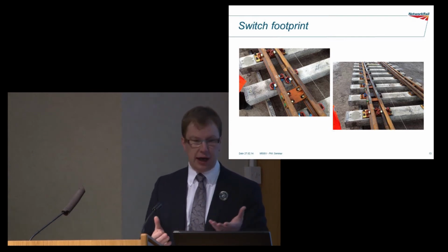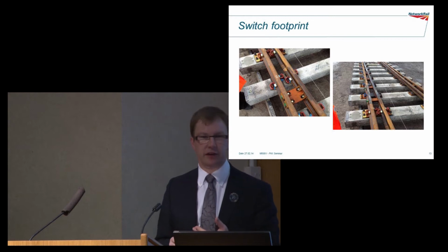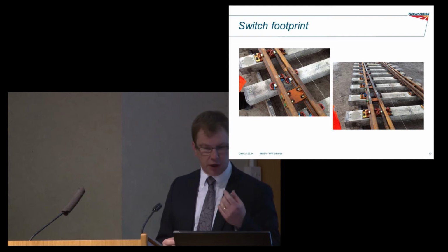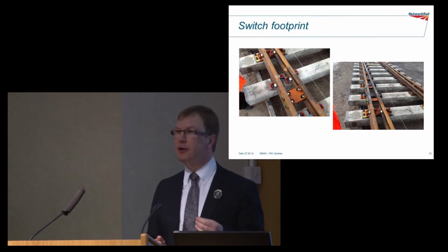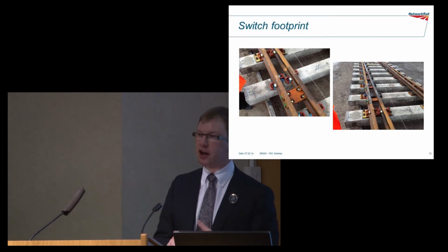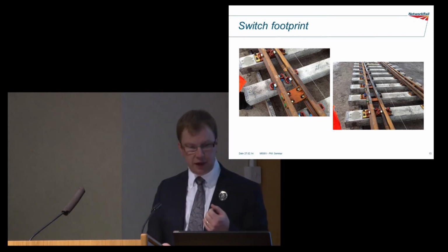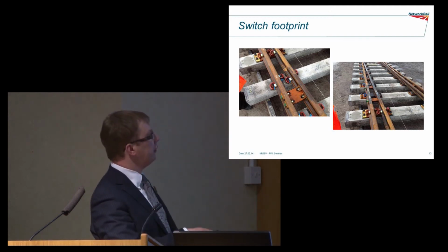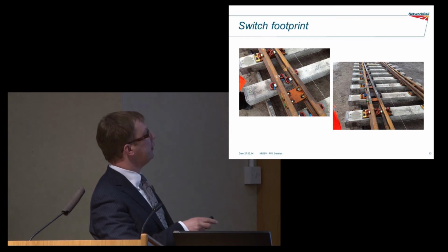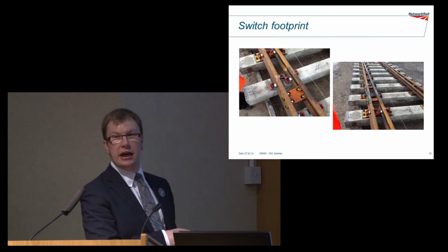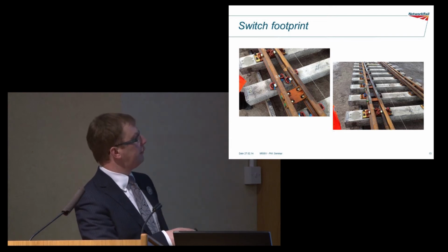And again, if we're not careful, if we create a new switch for NR56V, we end up with the same situation that we have with crossings. So it's holes in the bearers, but it's not just holes in bearers, it's also looking at where we go from base plates, because the slides are base plates obviously. There's normally then a heel base plate. I should just use a pointer. So here, if you see, this is a heel base plate, and this bearer here is the first direct fixed bearer, so there's no base plate in this location.